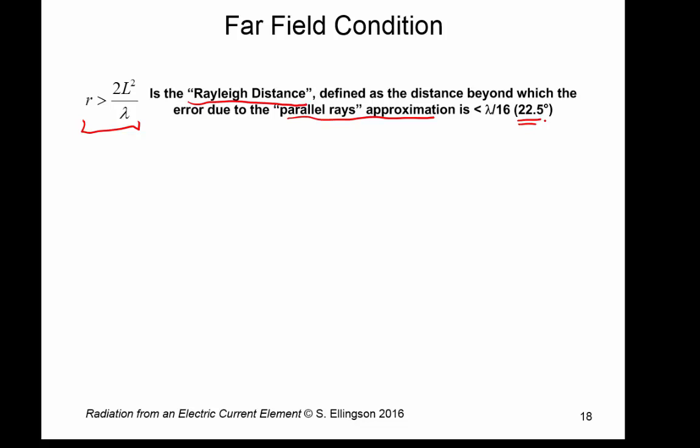Now, that phase error decreases, of course, with increasing distance between the source point or the current distribution and the field point. So typically, this dwindles very quickly to 0. But just being this far out gives us the result that the phase error is less than this. And in practical problems, you find out that really is sufficient to give us an excellent approximation to the actual answer.